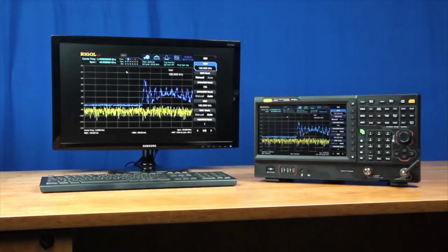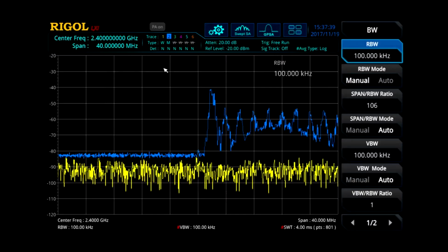Because the detector sweeps across the span, the instrument can't capture all the frequency components at once. Typical sweeping analyzer sweep times are measured in milliseconds to seconds. The RSA 5000 works as a sweeping analyzer for important high-accuracy characterization, but even in a fast sweep, it can't quickly show activity in the Wi-Fi or Bluetooth bands.